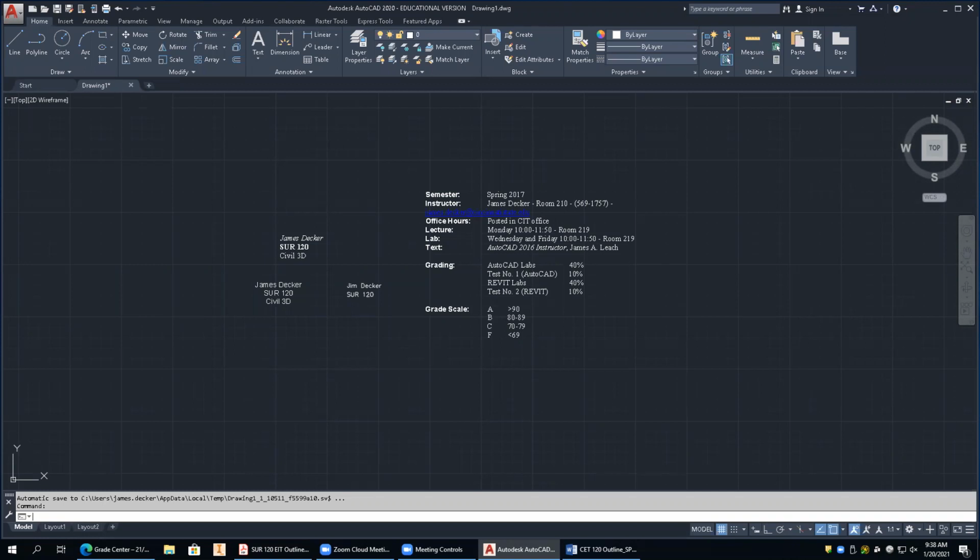And I don't have a distance here, but I'm going to suggest if you offset that line about 1/10 of an inch. Where those 2 lines cross, they now give you an intersection point that you can snap your justification point to. Do you see what I'm doing? I'm using these things to line them up perfectly, and then I can undo that or just delete it when I get done.